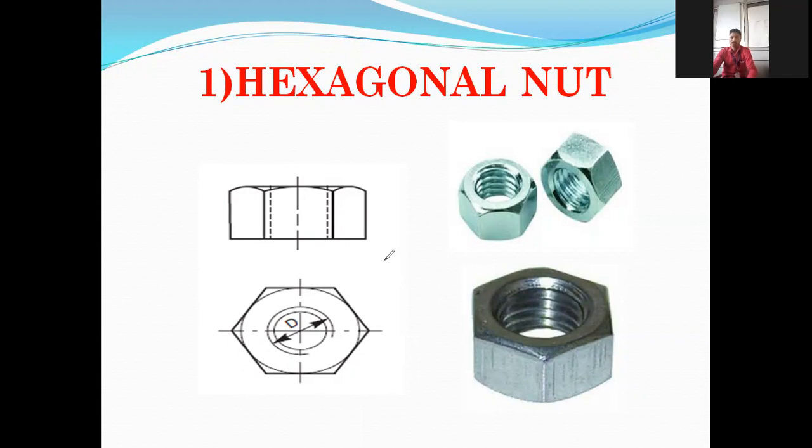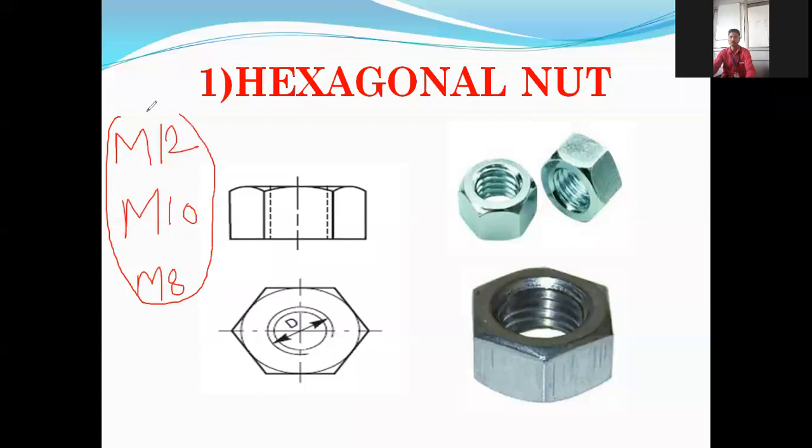What will a shopkeeper ask? So in terms of this major diameter or nominal diameter, immediately tell me the size. What will the shopkeeper tell me as the size of the nut? It may be 12, it may be M, where M stands for major diameter, M10 something, M8, you want M8, something like this. So this is this diameter D. It is not given in terms of number or in kgs, but it is given in this term. So it is specified in terms of size, that is this internal size, major diameter.